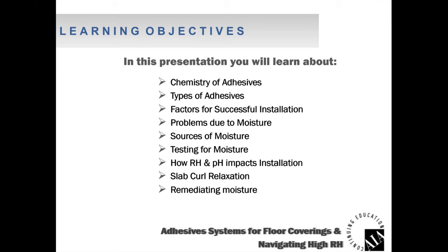There's a process called slab curl relaxation that I want to spend some time on too. This is something that you see on occasion out there in the industry, and it can get blamed upon the flooring installer when it's actually a result of excessive moisture. So I want to make sure everybody understands that, and then we'll wrap things up with regard to remediating moisture.